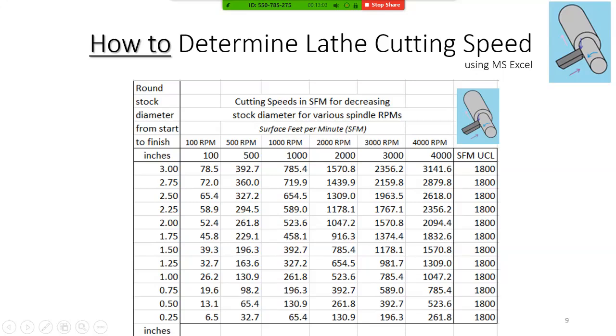We have what's the current diameter. Well, it starts at 8, and we can work down to 0.25 or stop in between if you're just creating a step down in the bar stock, like you were creating an axle inset for a railroad wheel going onto an axle. So it's going to look at the diameter, but it's also going to be using the RPMs.